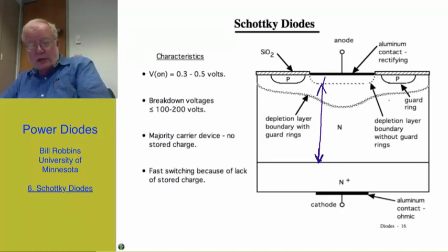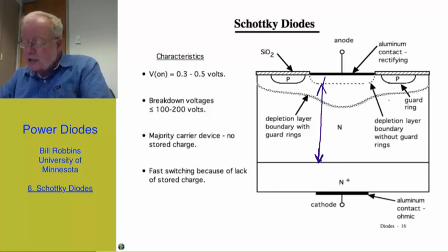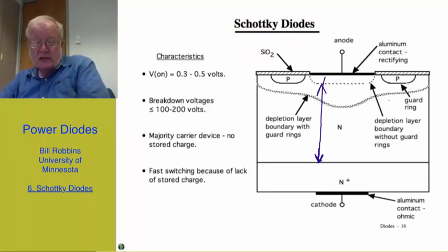It has to be more highly doped because we want to keep the drift region voltage drop to a comparable level as in the p-n junction diode. And without conductivity modulation, we have to have all those carriers brought in by dopants. So typically we would have this doped at several times 10 to the 15th to possibly 10 to the 16th in a Schottky silicon device.